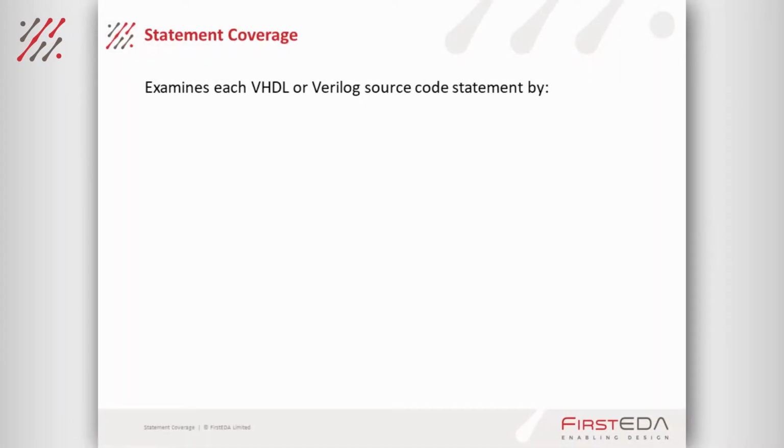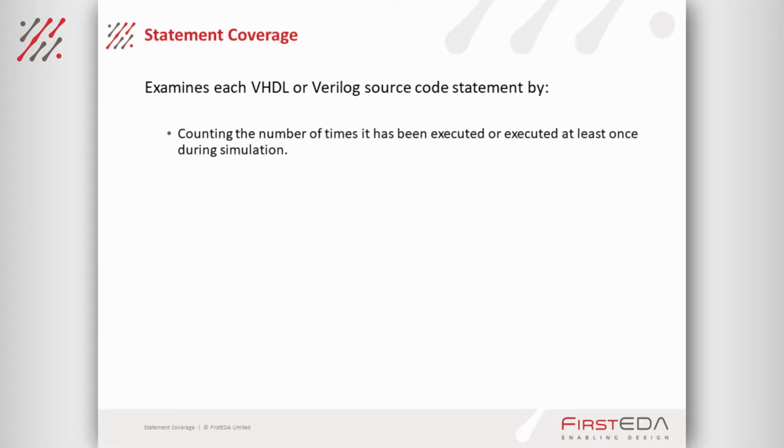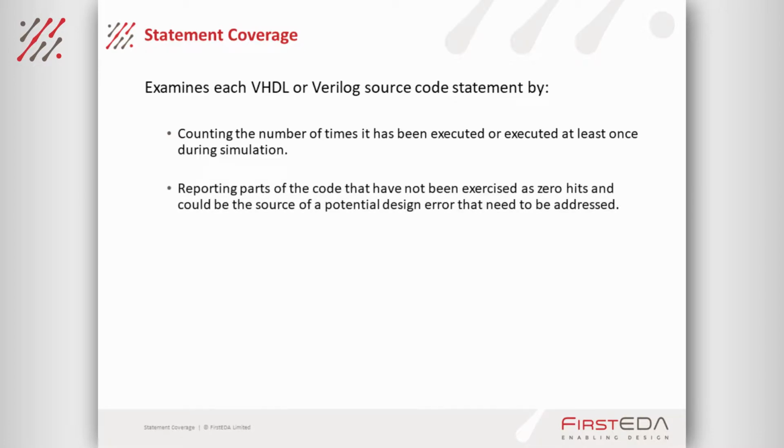Statement coverage examines each executable statement and counts the number of times it has been executed, or executed at least once, during simulation. A zero execution count pinpoints a line of code that has not been exercised, which could be the source of a potential design error.